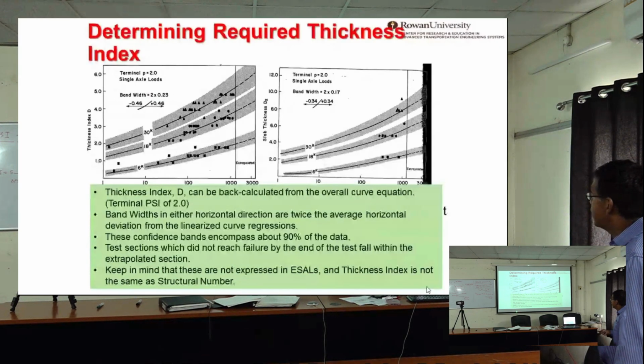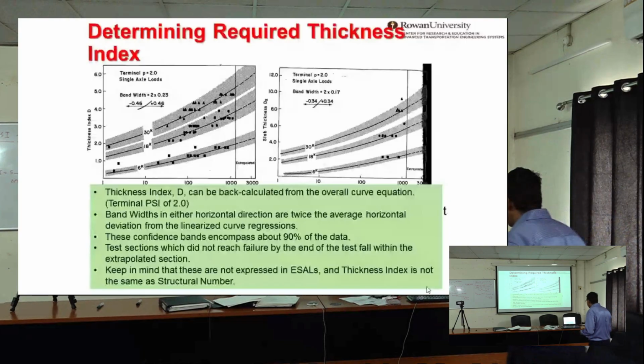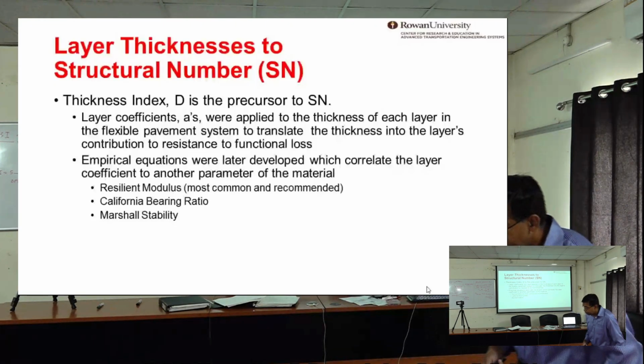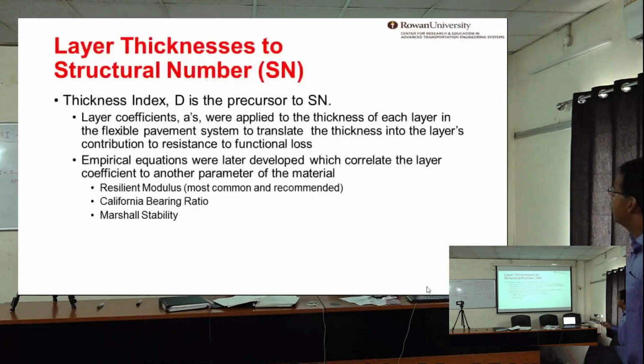Keep in mind that these are not expressed in ESALs. Thickness index is not the same as structural number, but it eventually became one in the next stages. Now let's relate thickness to structural number. Thickness index B is the precursor to the structural number. Layer coefficients A were applied to the thickness of each layer in the flexible system to translate the thickness into